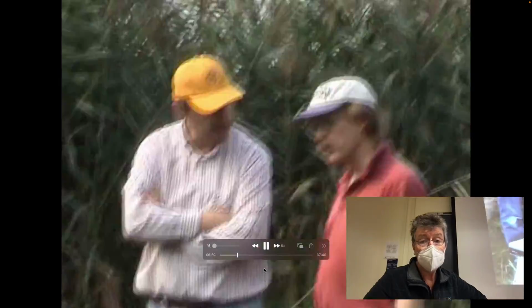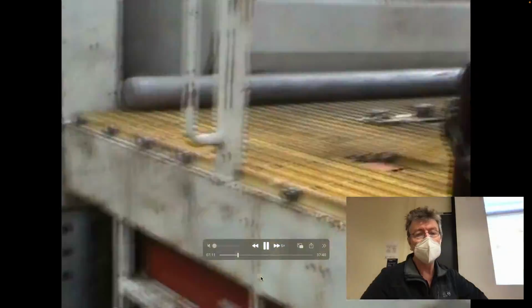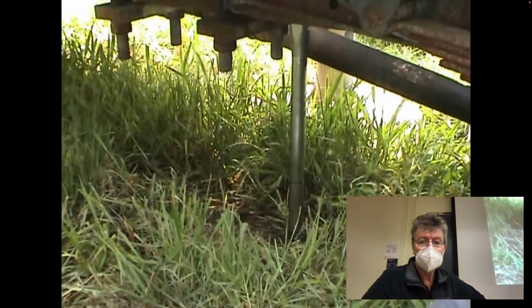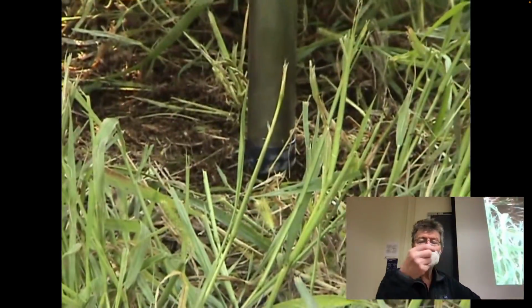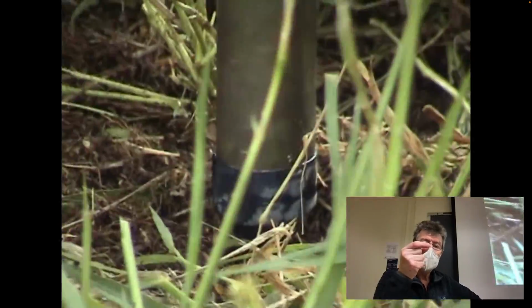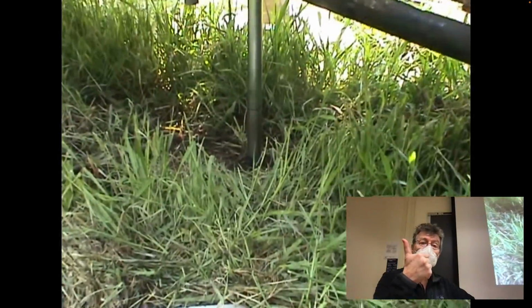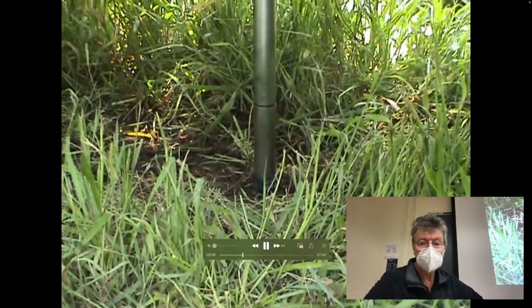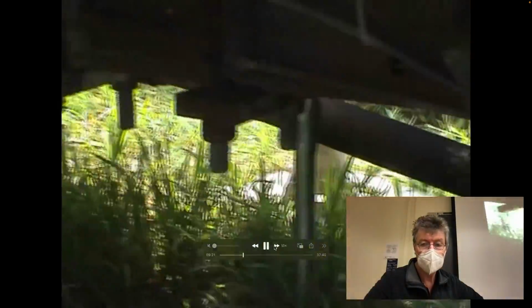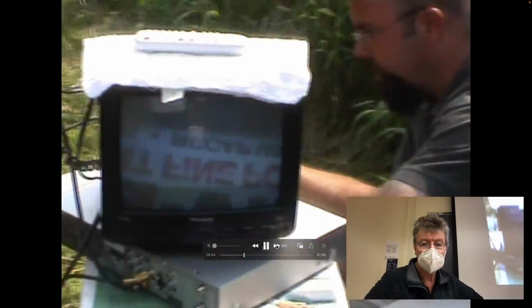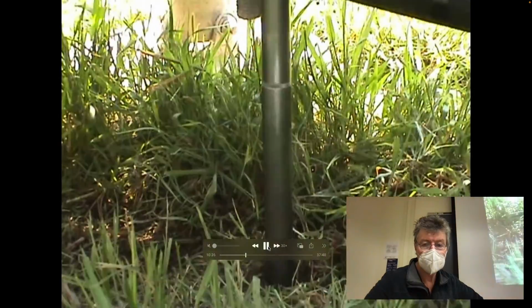This is a TV. The different thing about this is it's called the vizcone. As it goes into the ground, it has a small window in the side of it. The idea was that you can use this window to see what the soil is that you're going past. And instead of doing a grain size distribution, maybe digitally you can figure out exactly what the grain size distribution is within the subsurface. And also, if you have non-aqueous fluids, you can also see them moving around in the subsurface as well. So that was the whole idea of this.